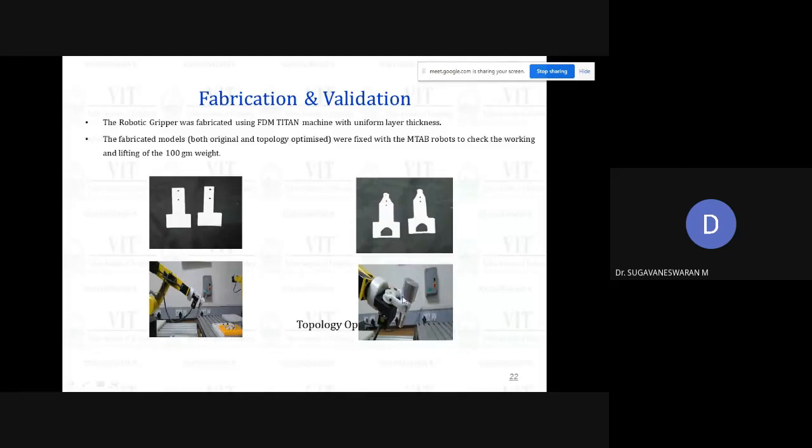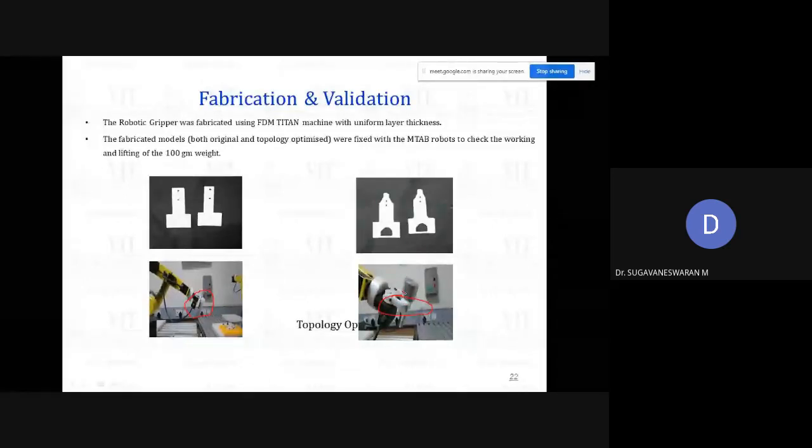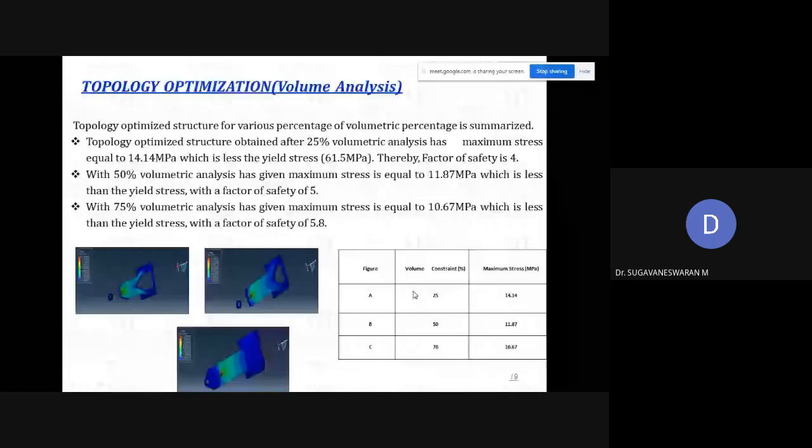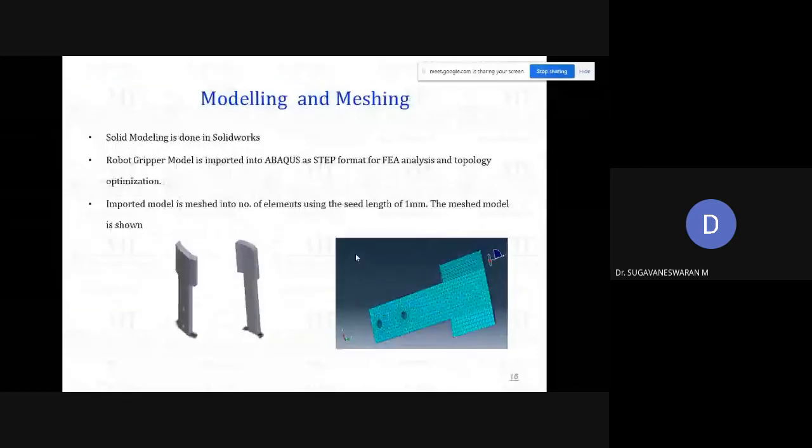So you can all see the gripper here, the white color material. Now this component has a certain shape, so I cannot use a flat gripper. As per the profile of the component, with its circular feature, I need an end effector shape, because the end effector should have a negative shape of your component. So that is the reason for this particular application; this is the end effector which comes along with the machine.